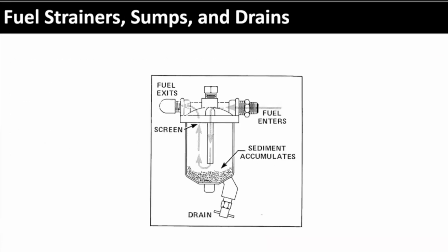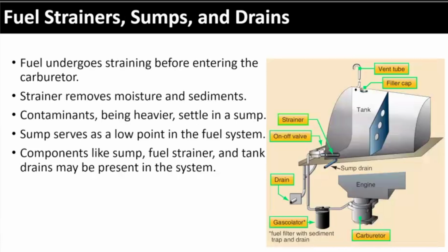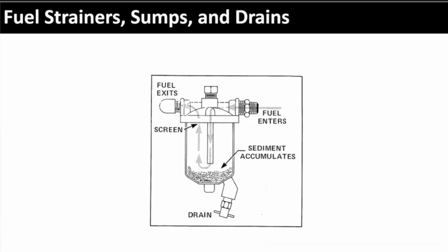Okay. Right, here's that gascolator. This is what we're looking at there, right? So the fuel comes in, goes down to the bottom. Anything that's heavy is going to settle down here and hopefully not make it back up through here into the engine. Okay. So again, second line of defense on making sure. You see a drain down there as well, right?